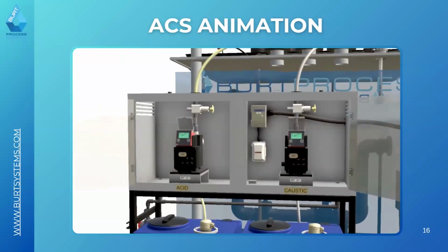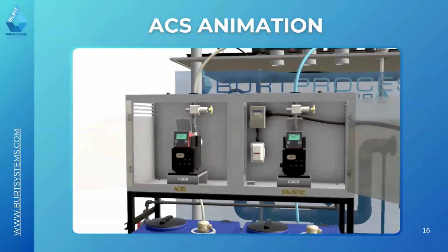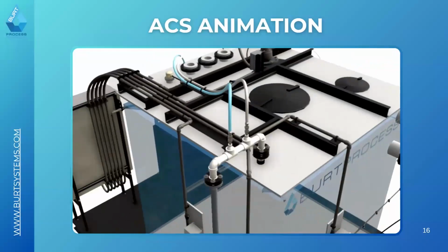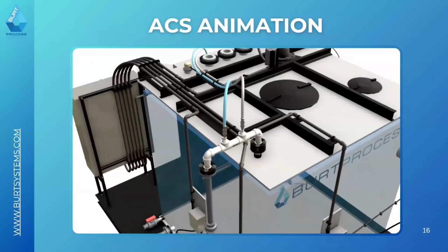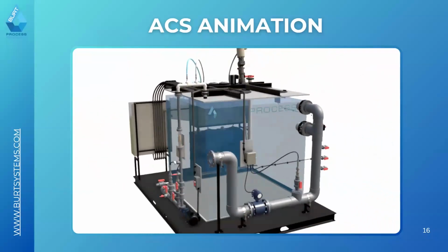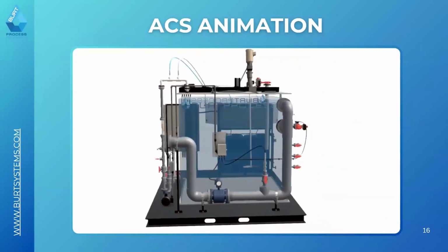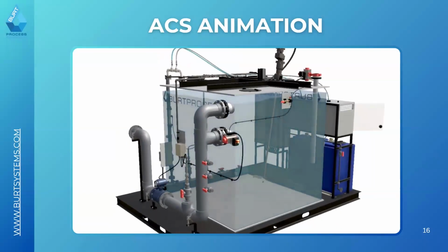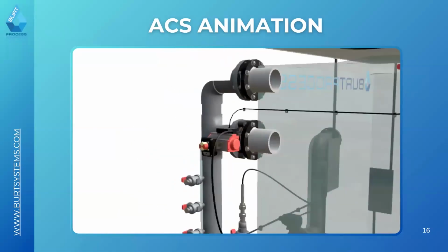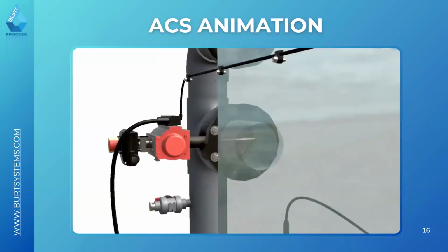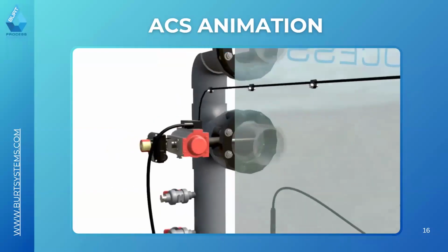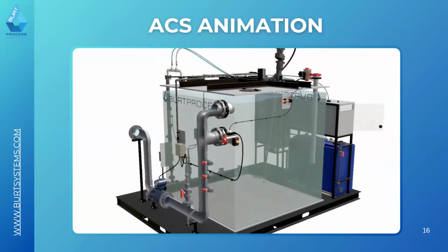So either they're collected upstream of a flow-through system. You don't necessarily want to combine them with all of the waste if you don't have to, because you need to further treat this. So if you have a few isolated processes, for example, that need to be biologically treated, or decontaminated, you can collect those separately, chemically treat them, and then transfer them into the bulk wastewater process.